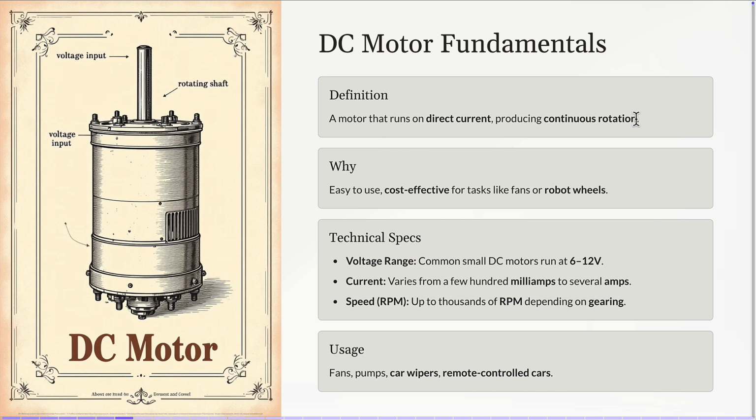And DC motors usually come with different technical specifications. So when you buy a DC motor, you need to know what input voltage is required. So some motors can work at 6 volts, 12 volts, 24 volts, 48 volts, depending on the thrust, depending on the speed that will be applied to this motor. And also the current, okay? The current, which says how many milliamperes. So some of the motors can work at 2 amperes.